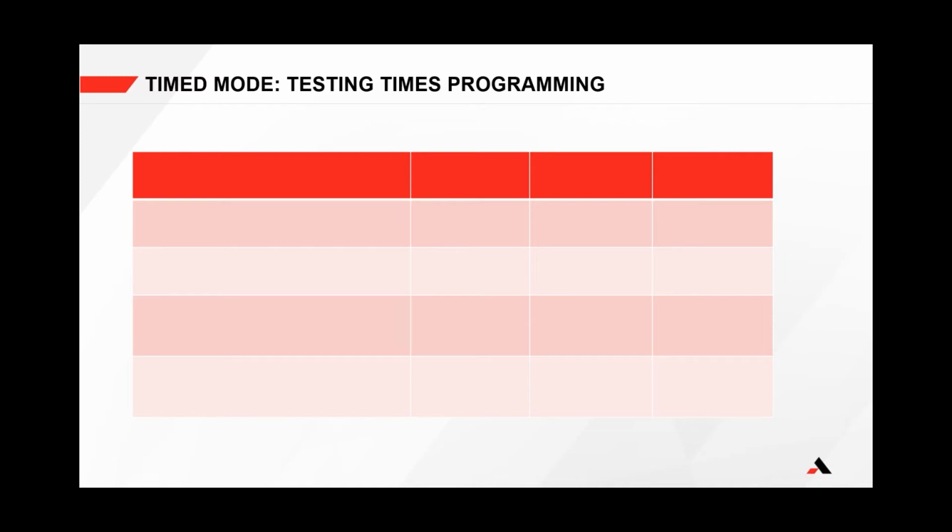When using auto test in hours of the day, there are 4 distinct hours of the day that can be programmed for checkback testing. Typically, at least one of the test times is set the same for all the UPLCs. Here's an example for a 3-terminal DCB line.